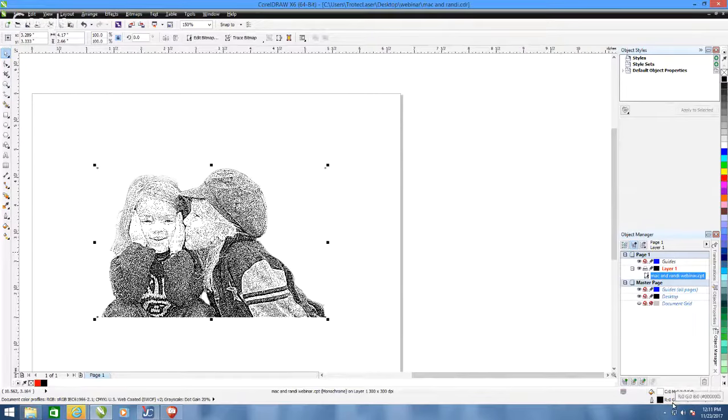You need to do this for the Rayjet. You also need to get rid of this white for the Rayjet, and the way you do that is you left click on the X at the top right hand corner, and you notice now I've got none right here. So for Rayjet, this outside line has to be RGB black, and the fill needs to be none.